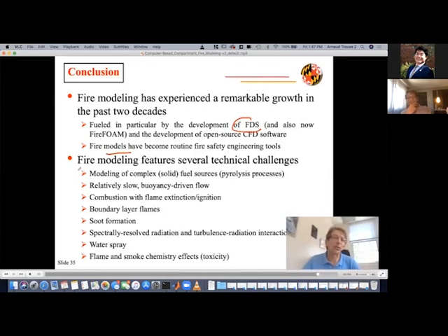And here, because I'm a fire researcher, I'm mentioning some of the hot topics in fire research. As far as fire modeling is concerned, there are still a lot of issues in developing pyrolysis models to describe the thermal degradation of solid fuel sources and the production of flammable vapors. There are also a few issues associated with the fact that our flow in fire scenarios is turbulent, but is typically featuring a moderate Reynolds number. So there are additional difficulties associated with this.